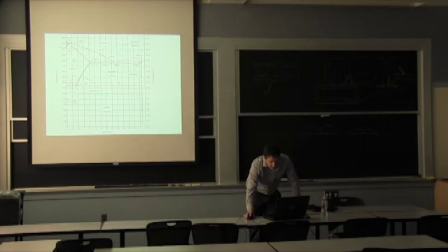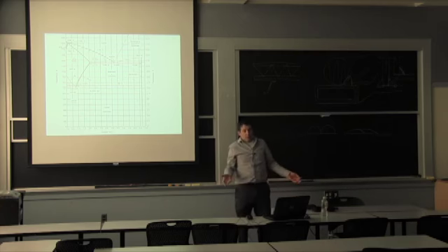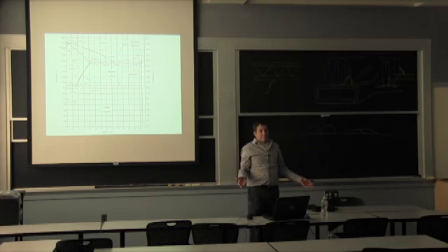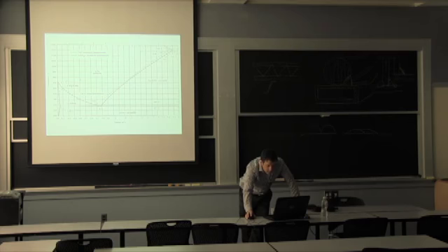So in the cast iron, you can see you get more of that cementite, and without getting into all the details, it's a good reason why it's making it more brittle. I mean, there are other reasons, but for today's lecture, all I want to say here is the whole phase diagram points you to a condition where you'd like to cast, and that's for cast iron. And when you go to the left-hand side is where we have steel, and that's where we're going to focus for now.